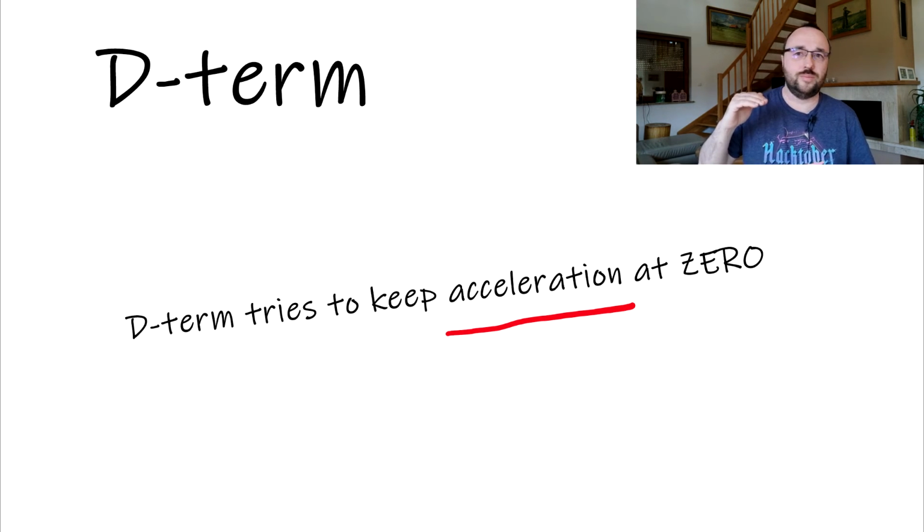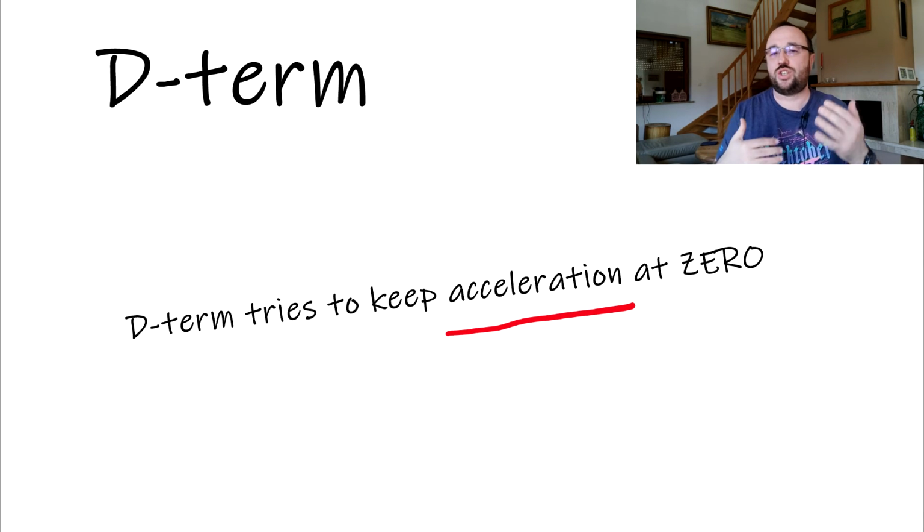Should be the more or less damped response or very rapid stop. This is also driven by the D term. But still, remember, this is only working with the acceleration. On the other hand, when the D term is computed from the error, then it changes the feeling, because it's not always damping. Sometimes it's even accelerating, making the feeling slightly more, how to say it, mechanical.